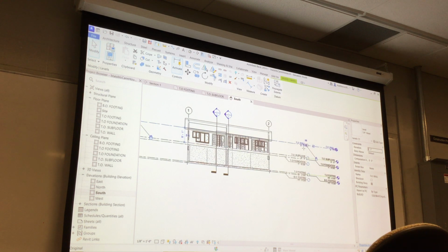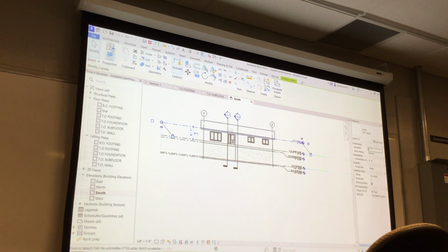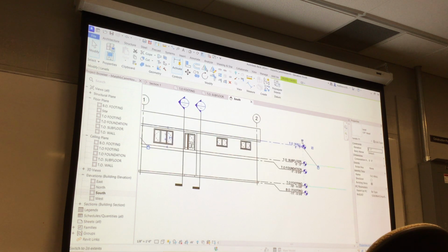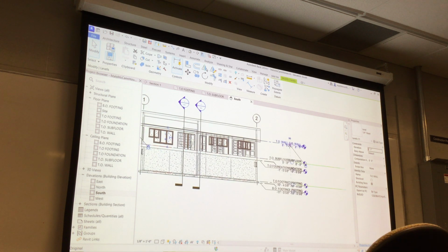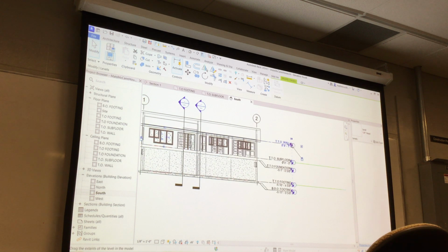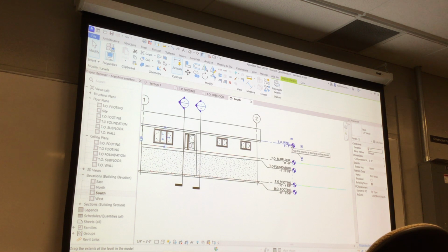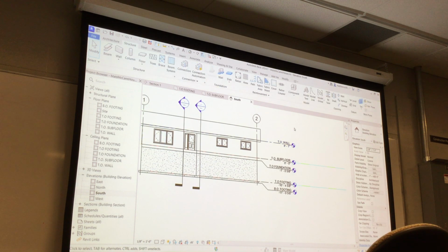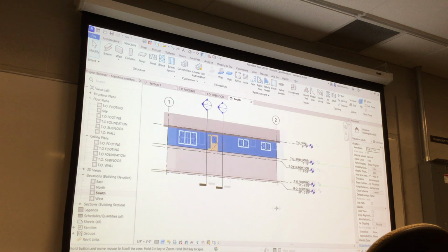So really what I wanna do is, I wanna go something like this. And I really wanna probably go like this. Okay, it takes a bit of fooling around to get this looking nice. Now, it works a lot better if you do a different scale, but right now we're kind of like that. Now remember, when you grab the top one of these elevation markers, they'll all move the same. If you start grabbing them individually, you're gonna pull them apart, and that's bad. Okay, but really to make this pretty, it should be fine, and it should be at minimum be shaded. All right? Okay?